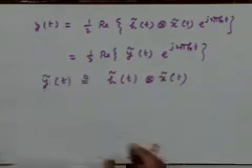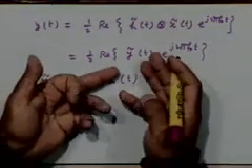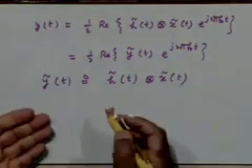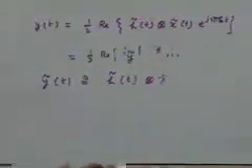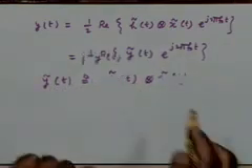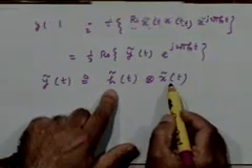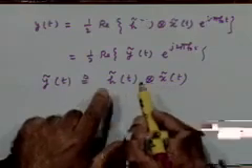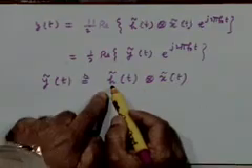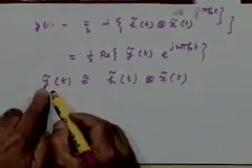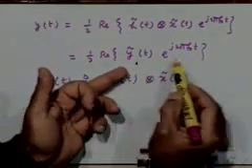We could have avoided all these lengthy integrations that we have just gone through if we had recognized this fact, and this is what I was trying to say in the beginning. I don't have to carry out a convolution of the bandpass signal with the bandpass impulse response. I could as well do the convolution directly of the low pass representation of the bandpass signal, the complex representation, with the complex low pass representation of the bandpass system's impulse response. Find out what the output would be, which will obviously be a complex low pass signal. Then go and do this operation.